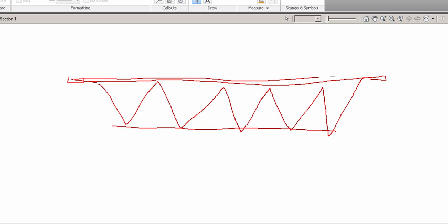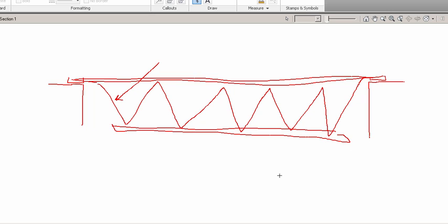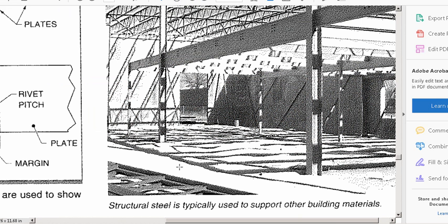There's typically some pieces of angle up here at the top and on the bottom, and there's a steel bar that runs up and down like this. Okay? They usually sit on frames like that, and there's no connection here or here. They just kind of hang out in space. But those are open web steel joists, which is what you see in the picture. But anyway, we're still talking about W-beams for right now, so we'll just stick to that first.